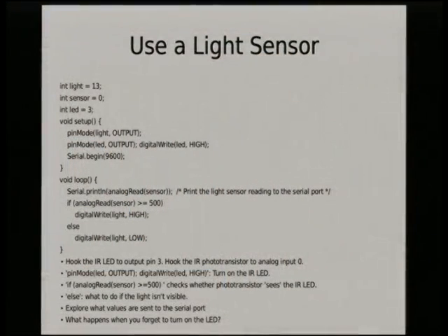And we talked about light sensors, and the key with the light sensor is this serial debugging line right there. You want to find out what the value is, because the value depends very much upon what material you're shining off of. In particular, we had a bunch of masking tape that we were using in one project, and one of the colors was bright white in visible light and black in infrared. It was really weird. In fact, one of the infrared sensors that I had saw one tape as brighter than another, like the values were swapped between the two sensors. Really? Okay. So the kids got to learn about the difference between theory and practice.